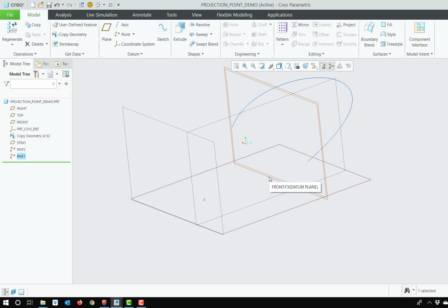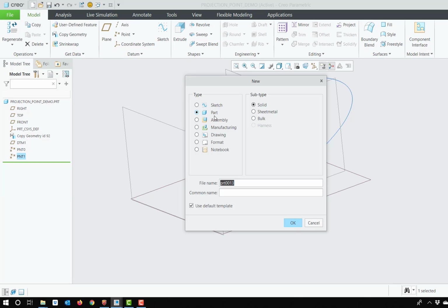Another update to Creo 6 is our default depth for extrusions. The way it's calculated to come up with your default value for extrusion has been updated to try to guess a more accurate value. What I mean by that is if I build a brand new part,